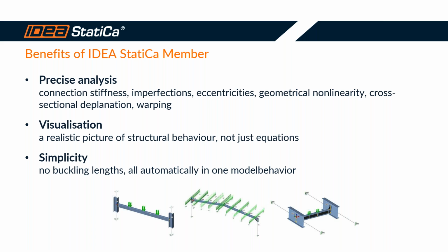But if that's not always the case, if you have other connections and members coming in, you don't know the stiffness of the connections, you have some geometrical nonlinearities or different cross sections, imperfections, that's where the added value is, and quite precise analysis can be done very quickly. The other advantage is visualization of the results.